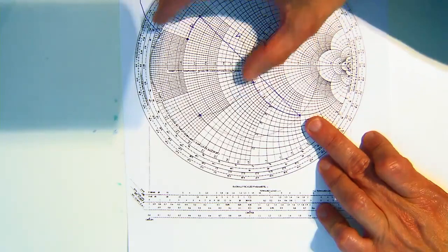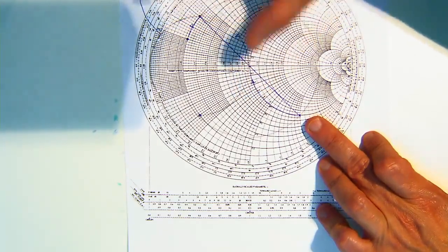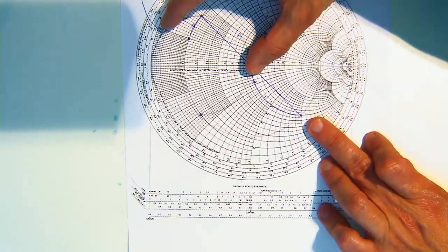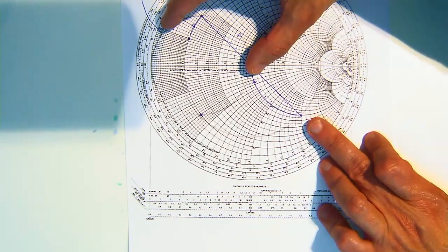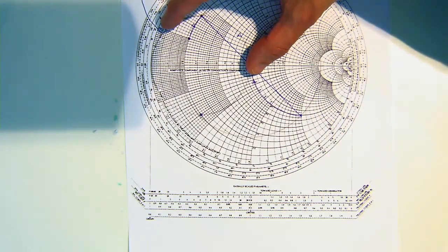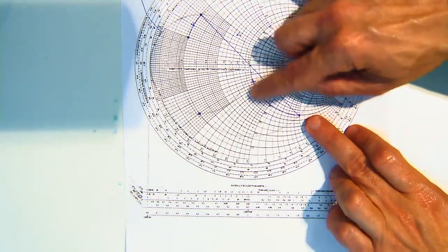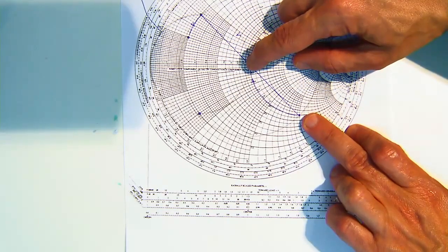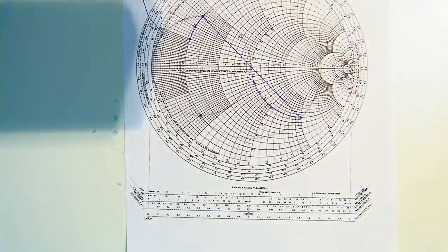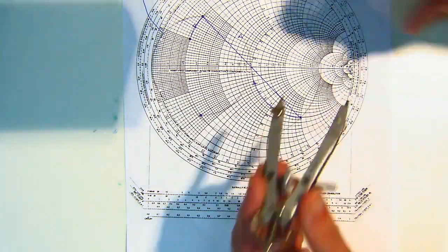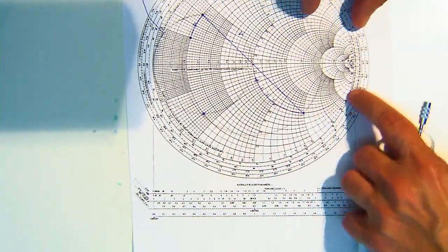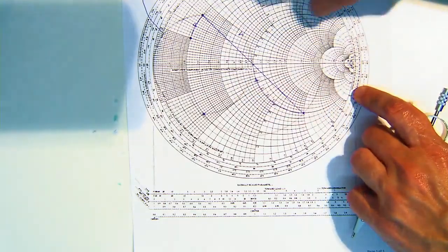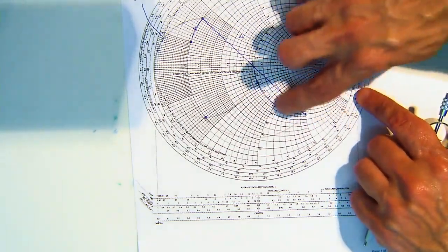So how can we do that? The only time we're guaranteed that is if we draw the line of constant admittance being 1 plus JB, so once we reflect, we know that we're going to end up on that particular curve. So how do we draw 1 on JB? Well, it's really simple. This is the line Z equals 1 plus JB, a circle of Z equals 1 plus JB, this circle here.